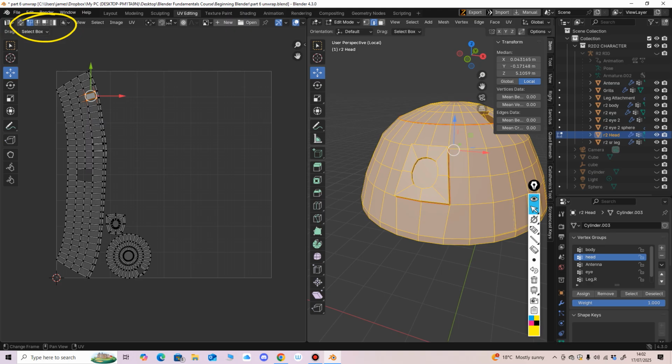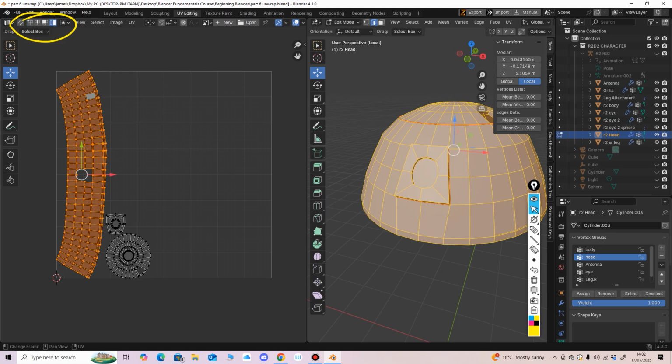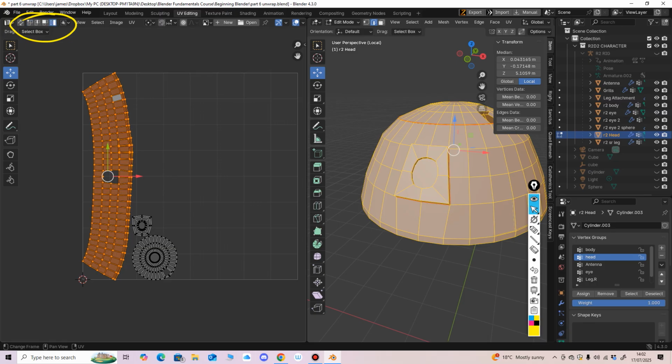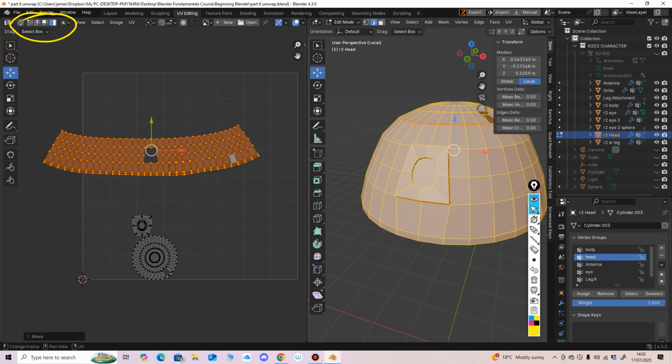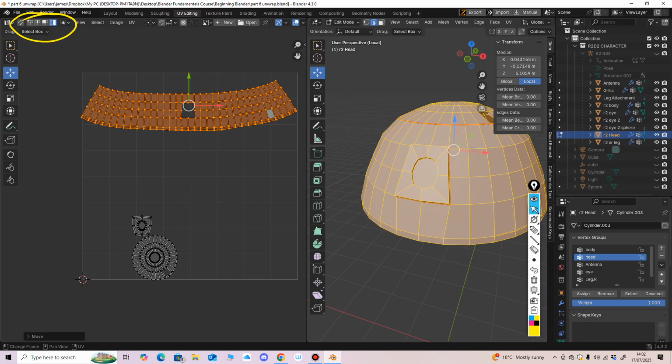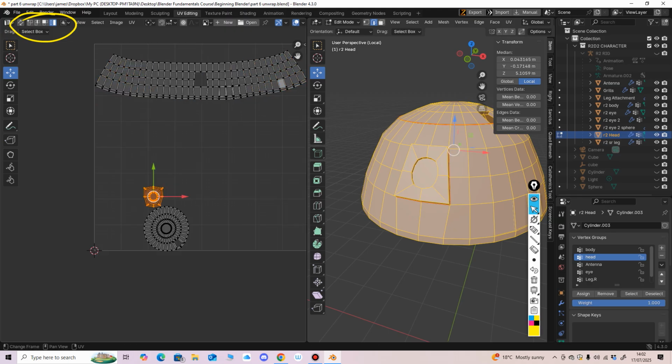Main thing you'll use though is UV island or vertices, them are the main two. Before you go to island, you can use the usual tools to make things look tidier. So you want to stay inside your UV tile. So that could be moved to there.